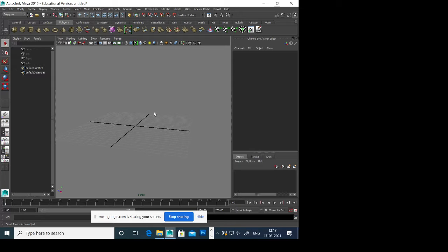And there is a main difference between polygons and mesh. I guess you know. Polygons are basically two triangles, and mesh also two triangles. But if you convert your model into triangles and export it, it will triangulate the entire model. If you have polygons, it will be two triangles combined as one polygon, right? So whenever you use mesh, it increases your vertex points, and when you use polygon, it reduces the vertex points. That's the reason we use poly.